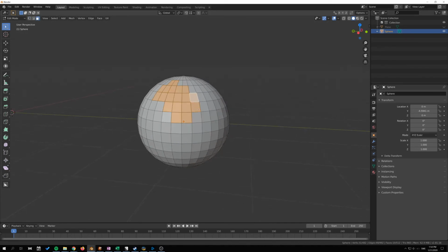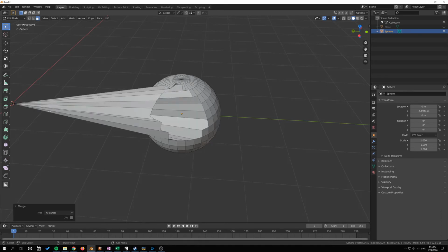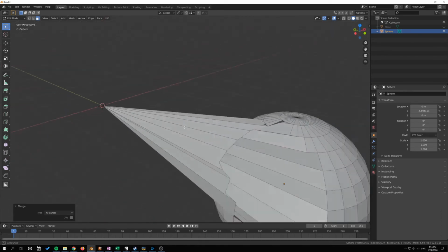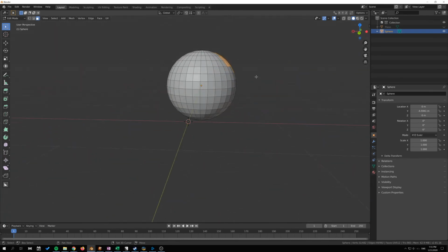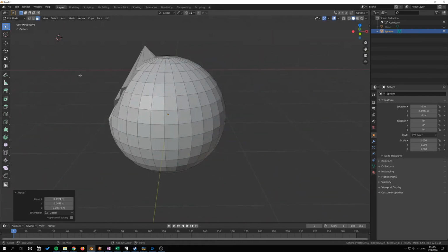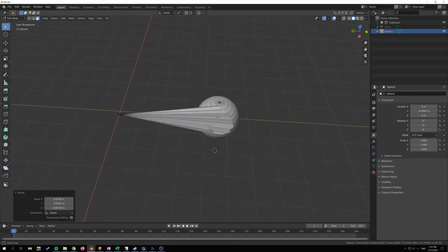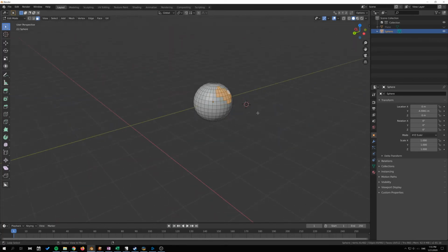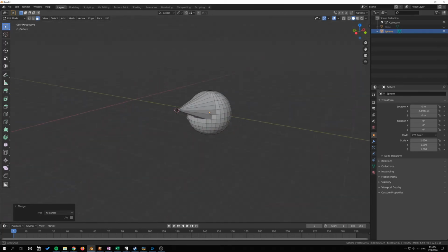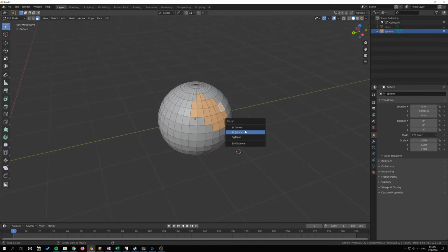So this is really a vertex tool. Add cursor, that will snap the vertex that's created to the 3D cursor. In this case it doesn't make much sense, but we can place this out here, Alt M, add cursor. Oops, that didn't make much sense after all. Let's see if we can get this in a sensible location here, like that. And then undo, Alt M, and add cursor. Something like that. Something that I very rarely use, but it's there, and in some cases it might be useful.